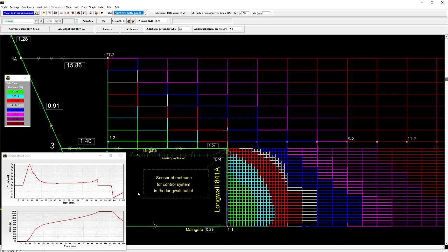So the shearer advances toward the middle of a long wall, and its cutting speed is changed accordingly to trends of the methane concentration of the shearer control sensor. The PID controller has been tuned so as to maintain this value within a safe limits.